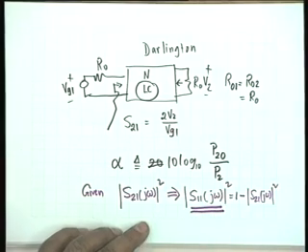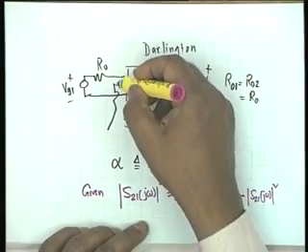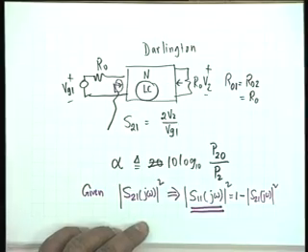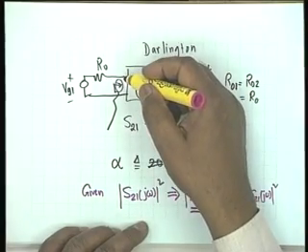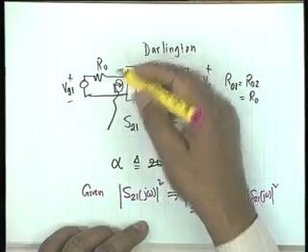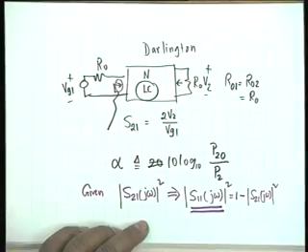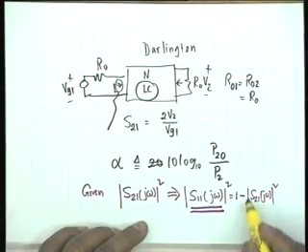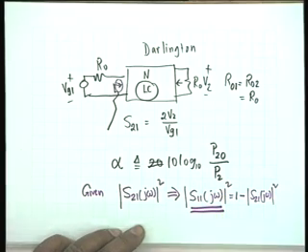So the transfer function synthesis problem, which concerns at least two ports, is converted into a driving point function synthesis problem. Isn't that right? S11 is the reflection coefficient at port number 1. It relates to the incident and reflected waves at port number 1.